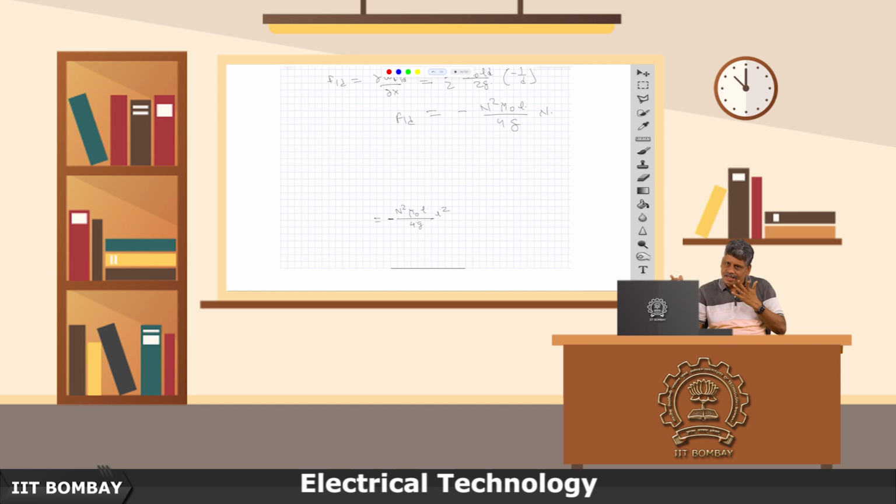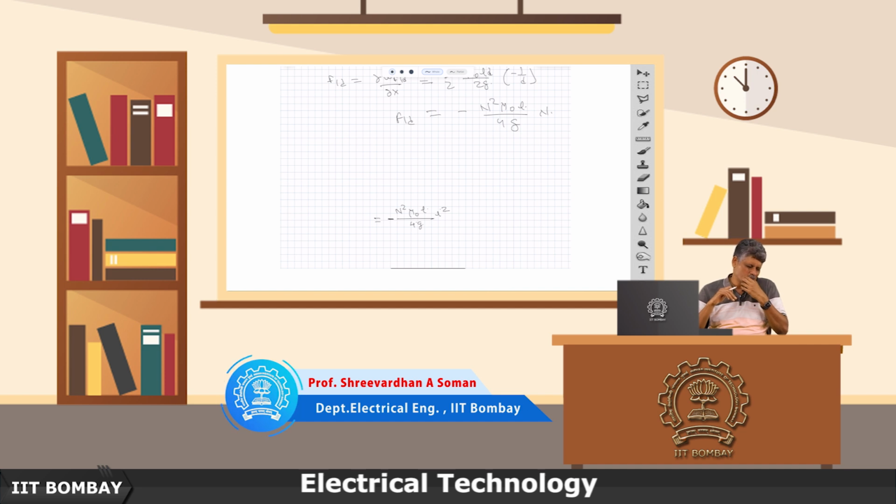Which one do I use? Many times, as we will see further, the co-energy concept seems to be more convenient to use. We are controlling currents, so we want current to be the state variable, rather than lambda. Instead of that, we are more happy to use current as a state variable. So, this is why we like to work in terms of co-energy. I think these two lectures connect your concepts of energy, co-energy and the field created force, which is happening due to change in the electromagnetic field or magnetic field.